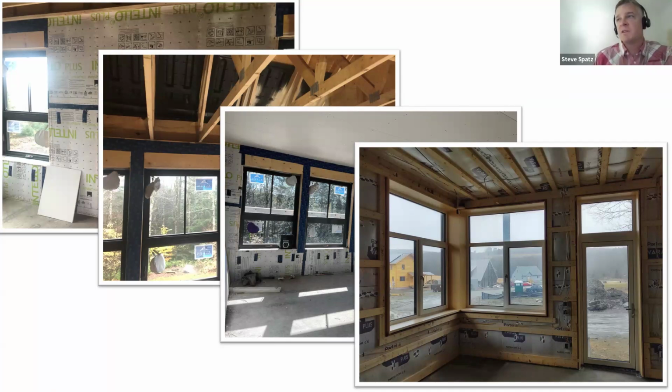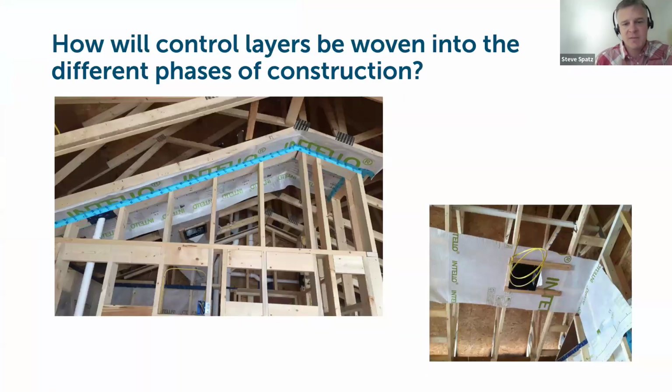For some thicker wall assemblies, if you're doing double studs, then strapping the interior of the wall assembly both helps with interior finishes because of the potential of bulging out of the dense pack layer, but also creates a potential for a service cavity where wiring and interior mechanicals can be run without penetrating into the insulation assembly behind it. But you can get high performing assemblies without taking these extra steps as well.